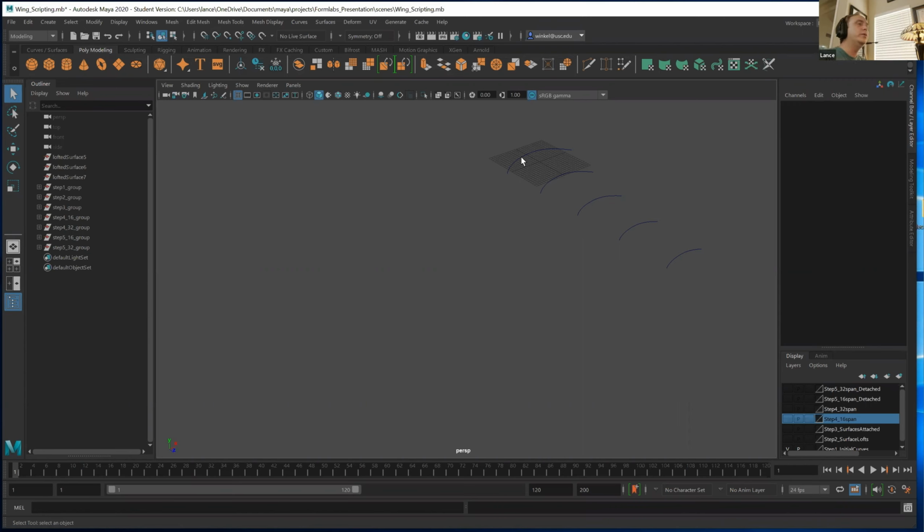CAD data, when you take out CAD drawings, that CAD data can be taken out and brought into Maya as curves. Also, if you take out a step file, which is a type of CAD file from a CAD program, when you bring it over into Maya, there is a step file importer, and that BREP file will get brought in as a series of NURBS patches. You might have to do some little maintenance stuff on the back end, but all of that data is directly translatable.